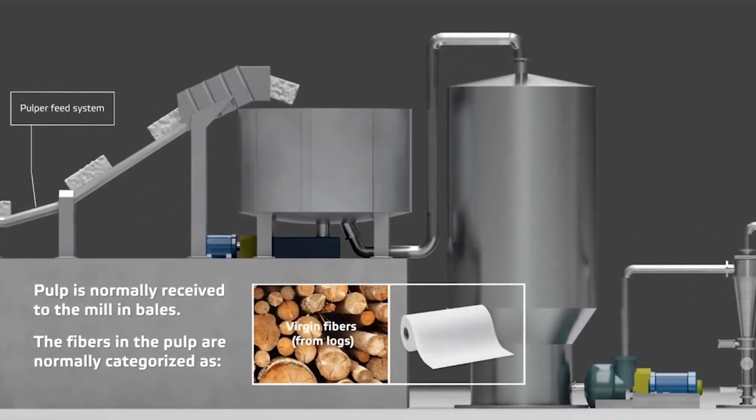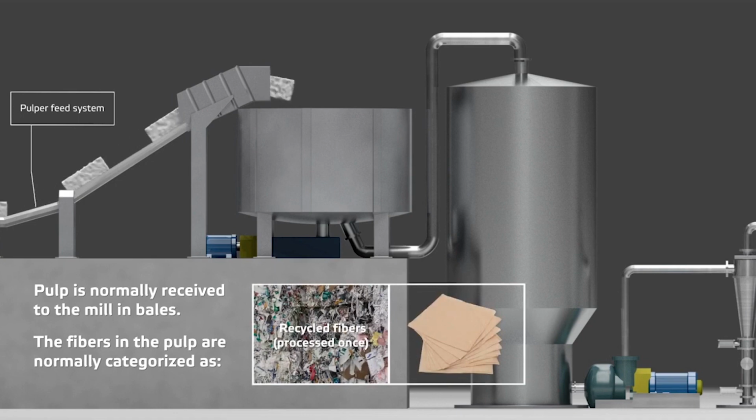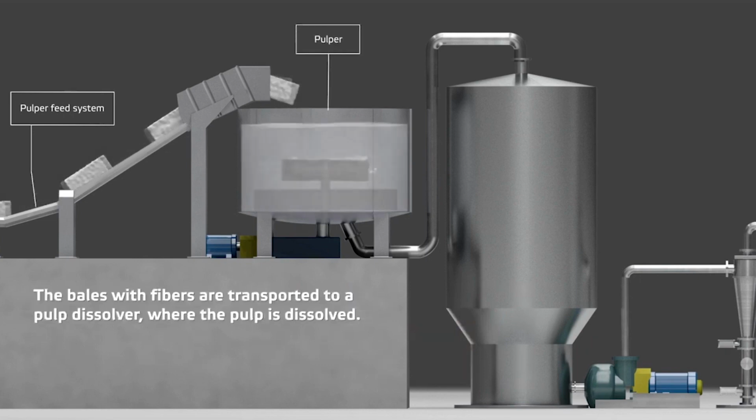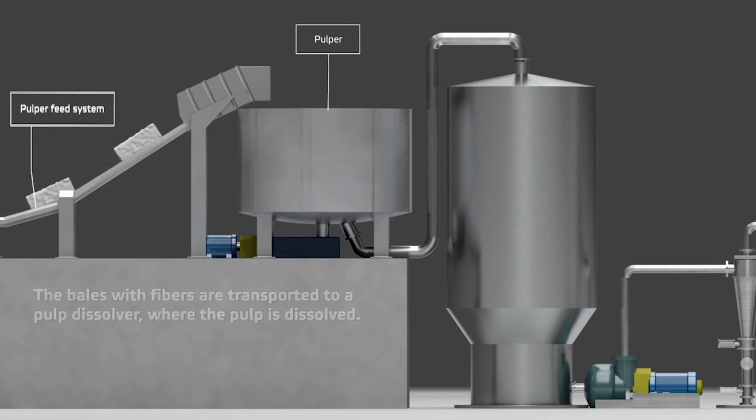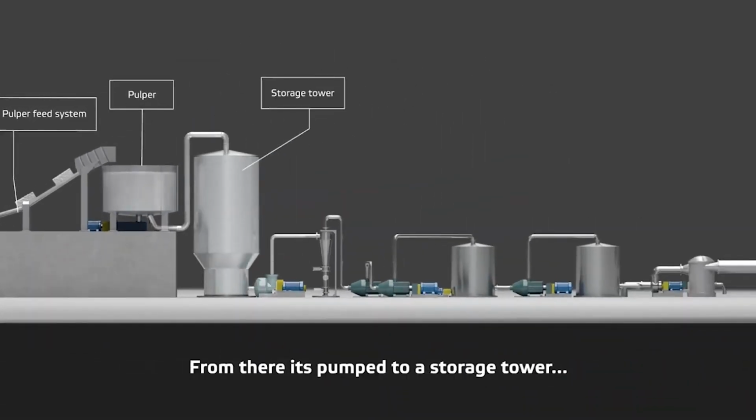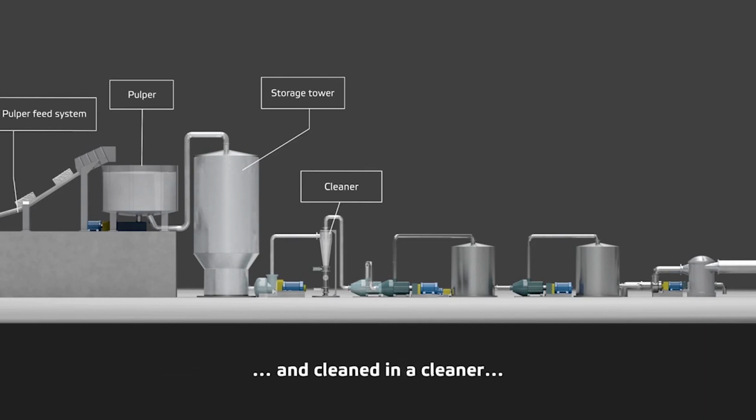If the primary raw material is wood pulp, it usually begins with the debarking, chipping, and pulping of wood fibers, either through mechanical or chemical means. This process effectively disintegrates the wood fibers into a pulp consistency, breaking them down into the essential building blocks for paper production. For tissues made from recycled paper, collected materials are subjected to de-inking and thorough cleaning to remove any impurities like ink, staples, and other contaminants.